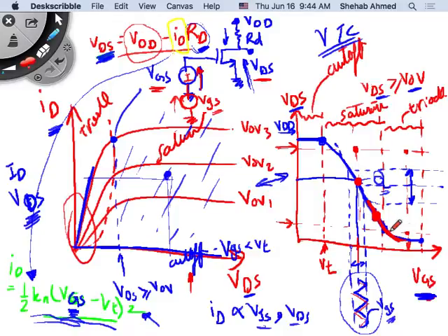Starting to hit the triode region, which means I will get distortion in my signal. Linear means if I put something in, I will get something that looks exactly the same shape, no distortion. But if I put a curve here, this value will be changed in magnitude with respect to the smaller value, for example. So if I operate close to the triode region, I get distortion. But I get a signal.